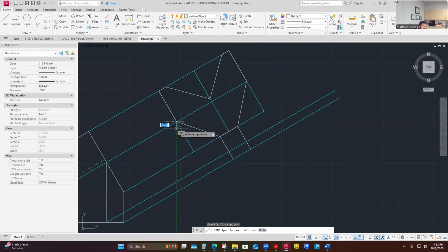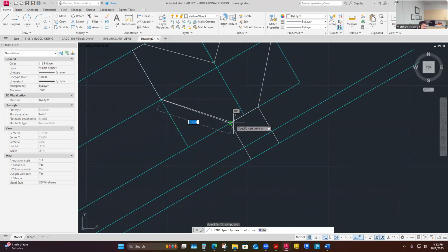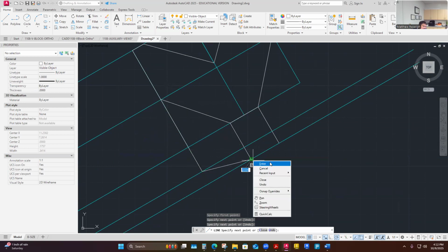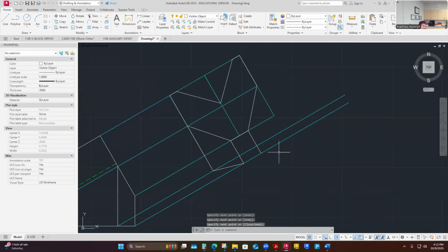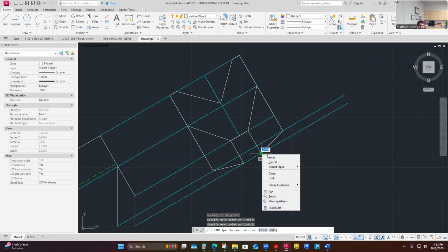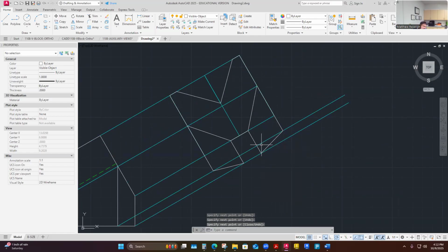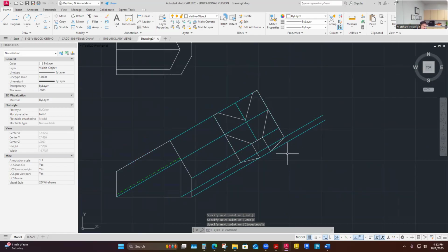That's the hidden line, nothing to do with what I'm doing here. This would come down to here, right? And then it's going to jump over to here. So this one's really going to come down and across where it intersects and then back this way. That's what it's going to look like, right? I think so. This is all foreshortened stuff. I'm not going to use it for dimensioning. It's the visual look of the full auxiliary view there.